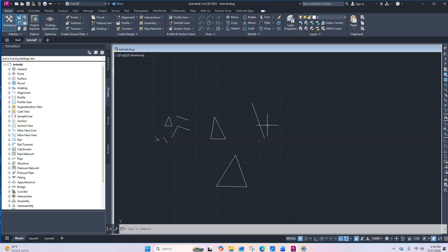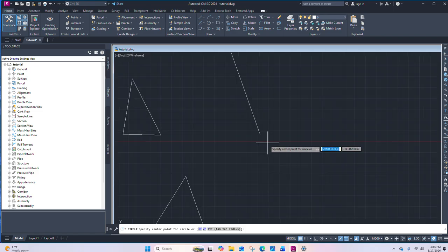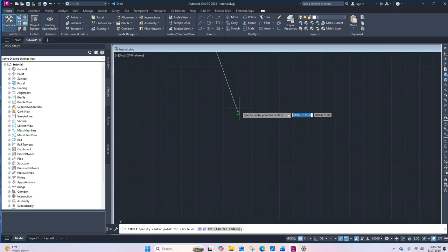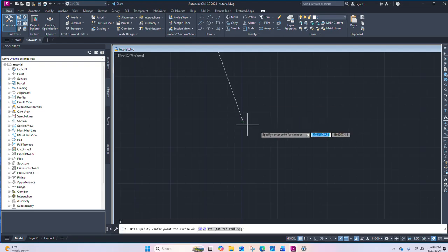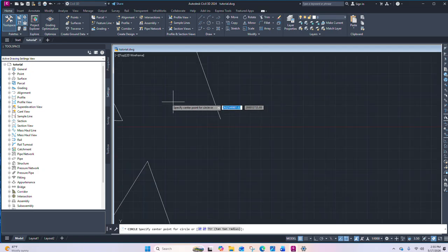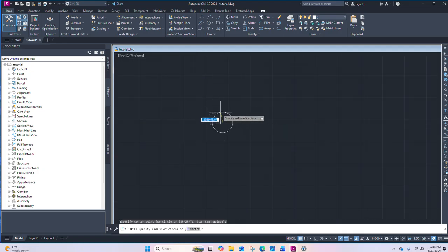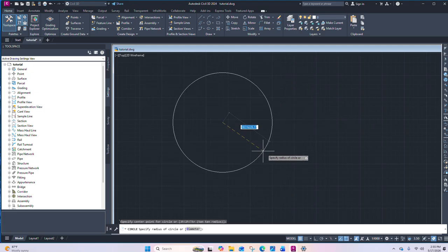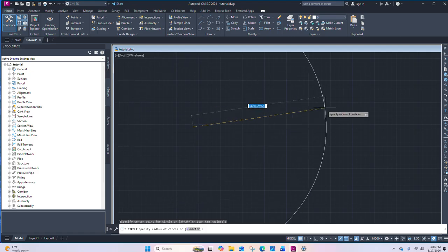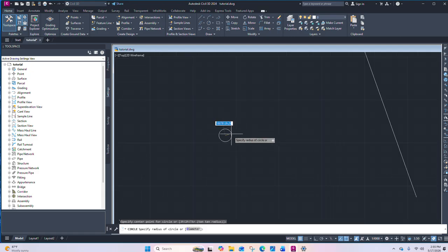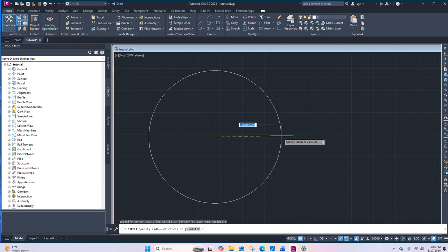It's very important when drawing anything, when coming up with different drawings. So the moment you select a circle and you click anywhere on the screen, you can move your cursor in any direction to change the radius of the circle, and you can enter the radius.